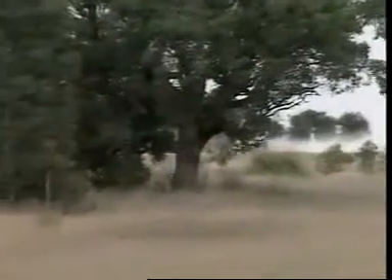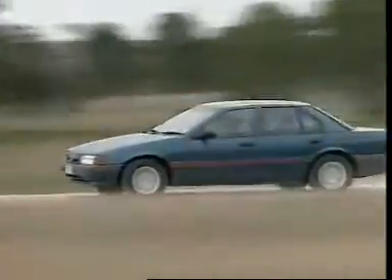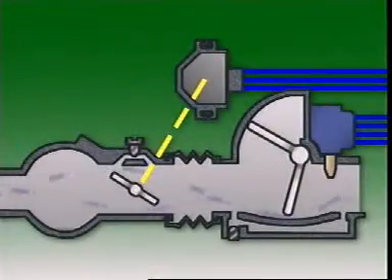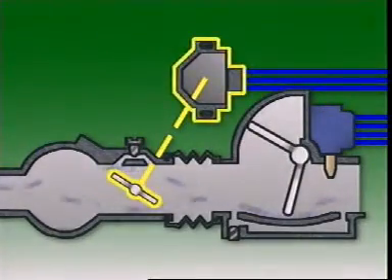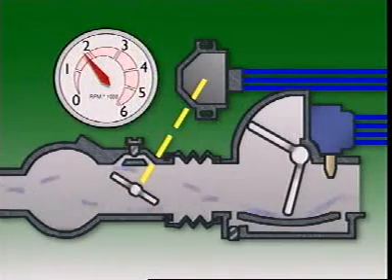This vehicle began from a cold start and has been running only a short time. It is now operating in top gear with a light throttle only. What influences its fuel requirements? A relatively small volume of air is entering the engine. The throttle position is associated with economy or cruising conditions.